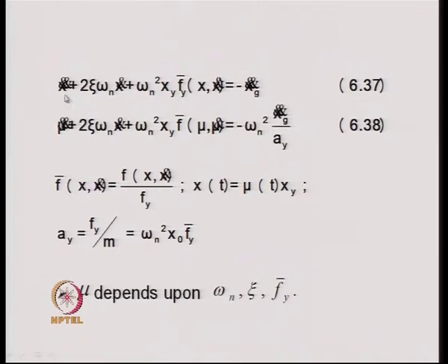That is, we have the acceleration, we have the damping term, and then we have a function; instead of writing kx for the linear system, one should write a function of x and x dot, which is a general function showing the resistance of the structure at different stages of loading, including the elastic phase and the inelastic phase. This is equal to minus x double dot g.